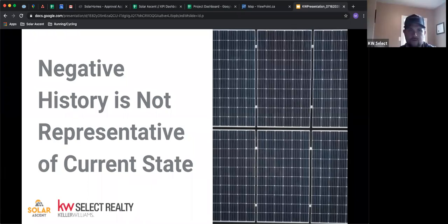Yeah, that only makes sense. It's not a big deal to do it after the fact, but you're doing a lot of rework. And where solar covers the most exposed parts of the roof, the array is going to help protect it to a certain degree too, because that south side's not going to get pounded by the sun. In a lot of cases on an asphalt roof, any strong south facing roof face, you'll see that part of the roof go before the more northerly or more shaded parts.